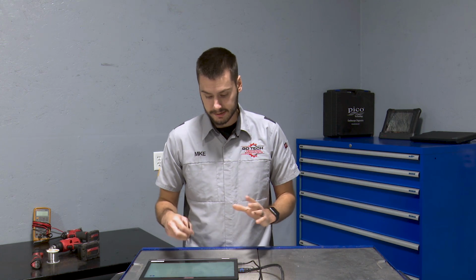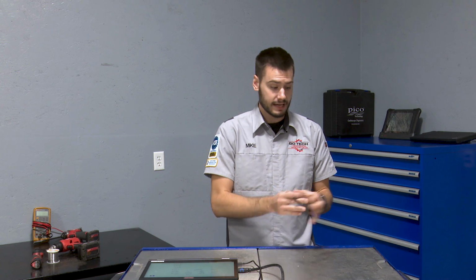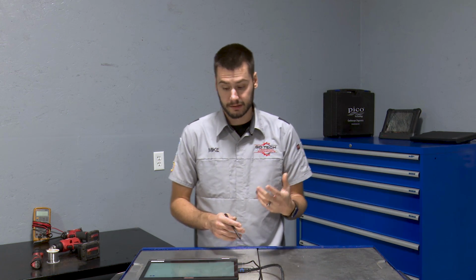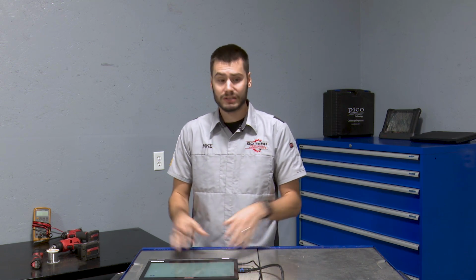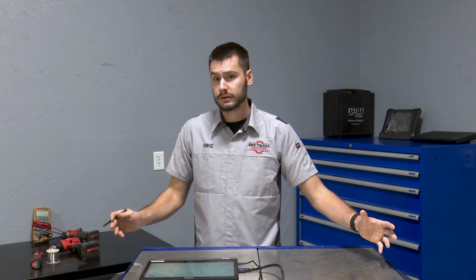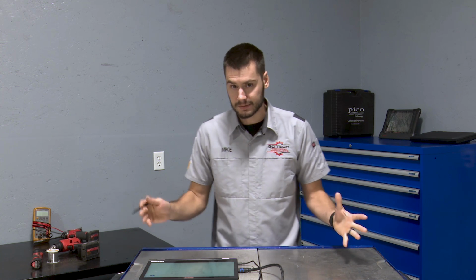Before I had the ability to do it digitally on my laptop, I would take diagrams from each of those systems, from interior lighting, power windows, radio, and cluster. I'm just going to take those 4. I would take them from each of the systems he's complaining about, lay them out on my bench, and try to find the commonality in all of them. There's likely going to be 1, maybe 2 components in each of them that's the same across all of them, right? Because when one goes out, they all go out. It's unlikely that they're all going bad at the same time, okay?